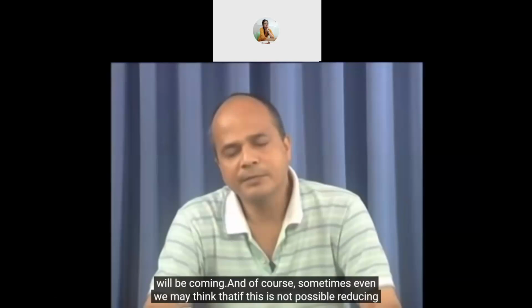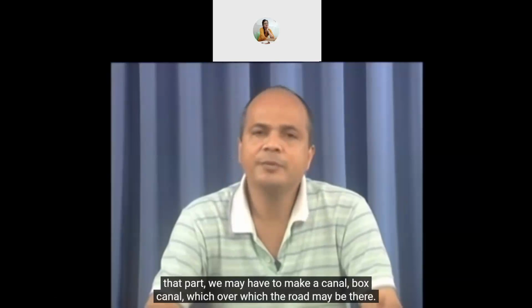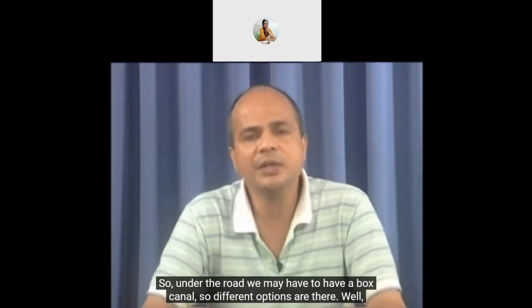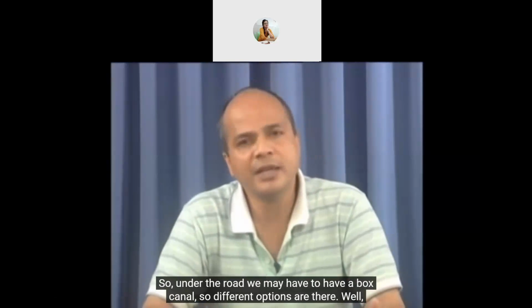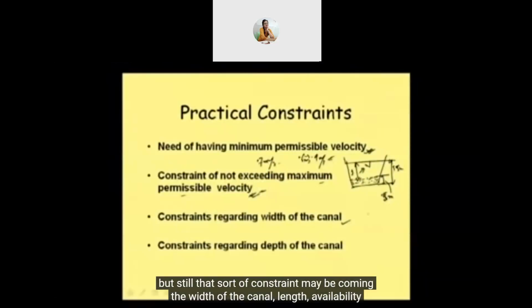And of course, sometimes we may think that, okay, if reducing that part is not possible, we may have to make a box canal, over which the road may be there. So under the road, we may have to have a box canal. So different options are there. Well, but still, that sort of constraint may be coming, the width of the canal, land availability, and all these things. And sometimes there is, suppose, a constraint against depth of canal. Well, that is also another constraint.